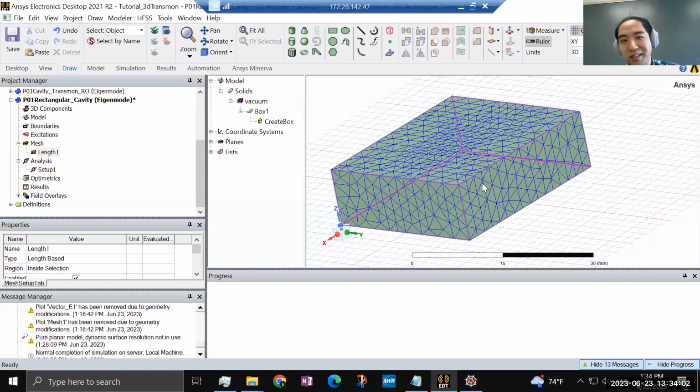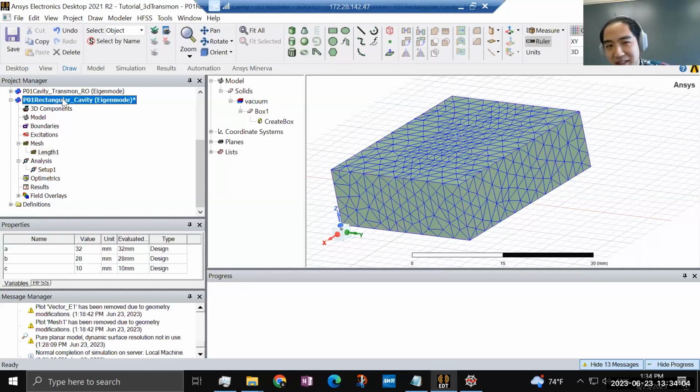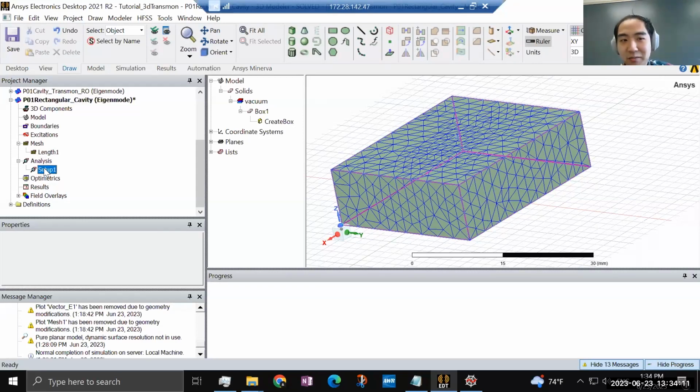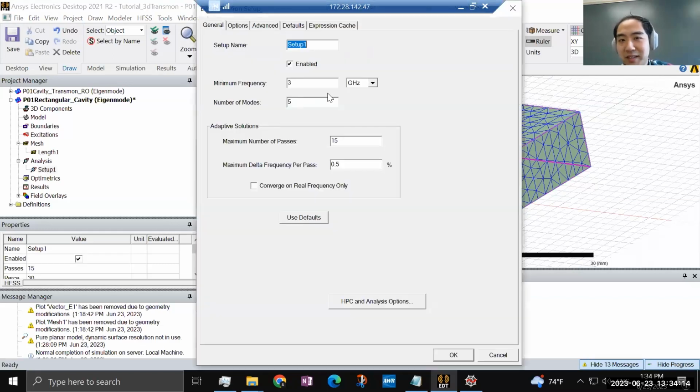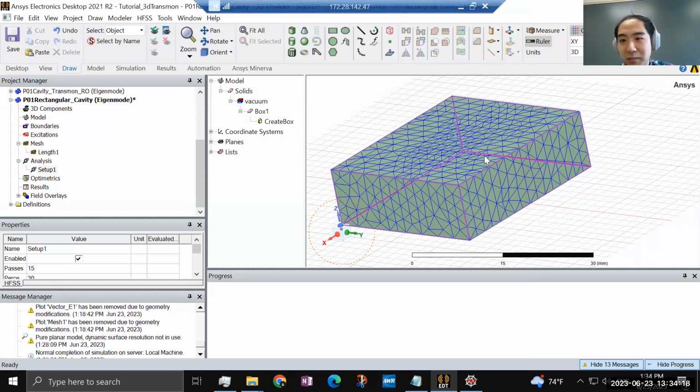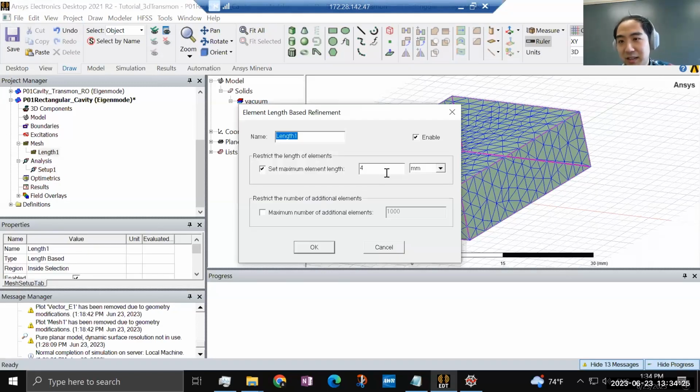You can't do it here, because the way HFSS works is that when it has run the simulation, it will remember this final mesh. When you modify this setting and run it again, it will remember the mesh that it created from the previous job. But if you start from scratch, make the same design and give it a different initial meshing seed, then in principle, that should have no influence on the final result it converged to, because the initial meshing should not matter for the electromagnetic solution.